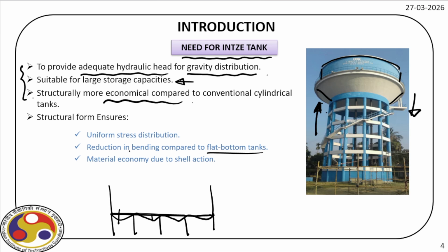Not to that extent, it is reduced by a significant amount. And of course, because this stress is uniformly distributed and reduced compared to a flat bottom tank, the material is judiciously used, and there is a certain economy of using this type of geometry so far as the material usage is concerned.